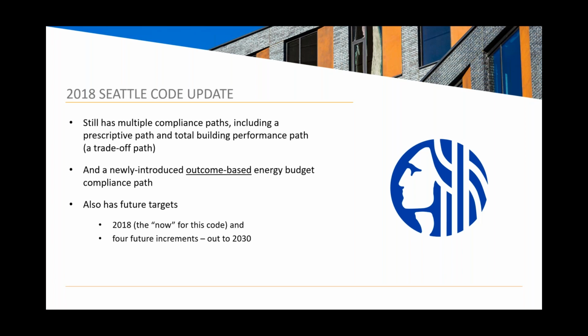But it has a newly introduced outcome-based energy budget compliance path, which is the one that is more similar to the BC Energy Step Code, and it's the most flexible physics-based version. So we're really glad to see that come into this building code, and we think that eventually it's going to be the prevailing method for compliance, even though it might take the industry a few years to adopt it as the majority choice.